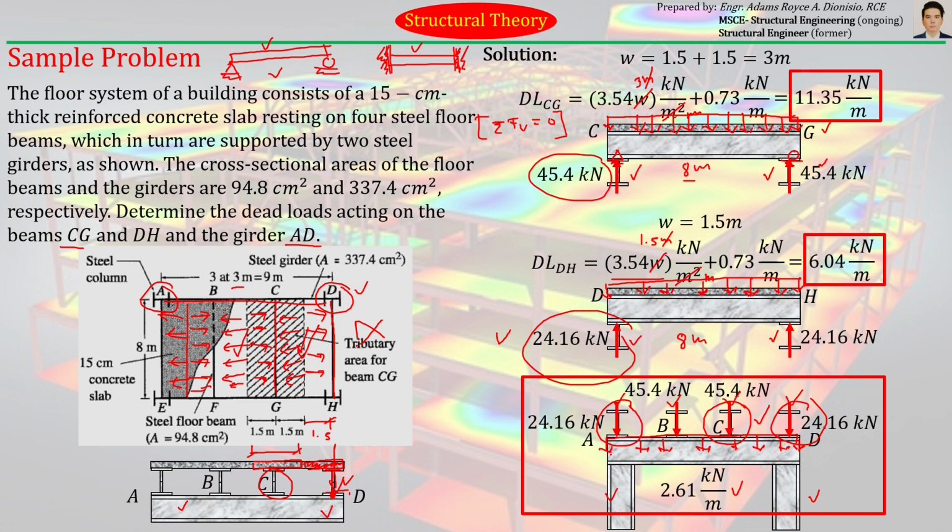The girder AD is connected to the column rigidly like this. So, it should have a vertical reaction and a moment there. But if you only want the vertical reaction, it is fairly easy to get. It's just the sum of the vertical loads being carried by girder AD divided by 2, because the two supports carry equal loads.